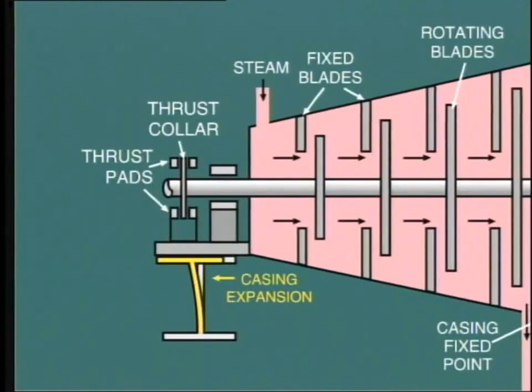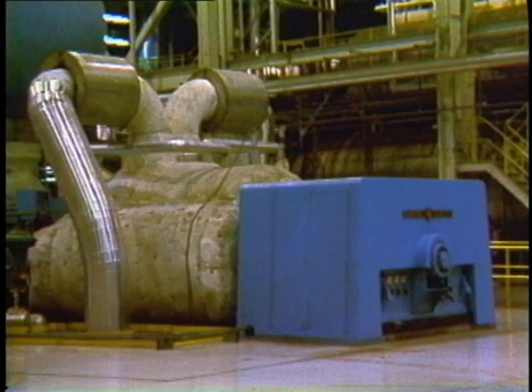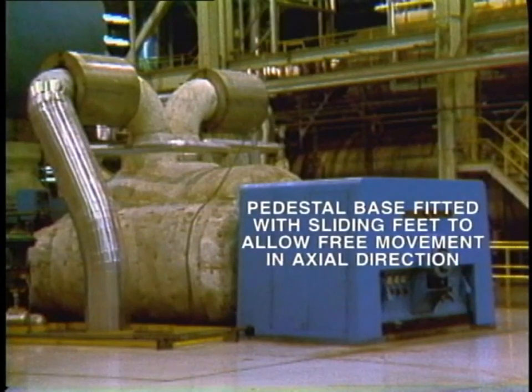In this particular machine, the pedestal is fixed to a flexible support which allows the movement to take place. A more common arrangement on larger machines is to fit the base of the pedestal with sliding feet to allow free movement in the axial direction.